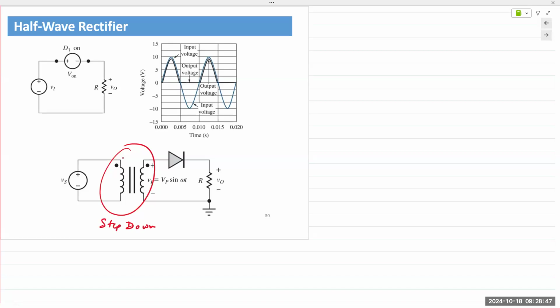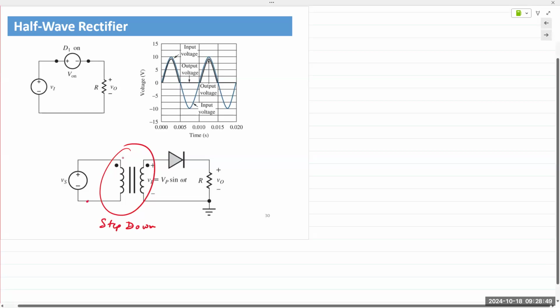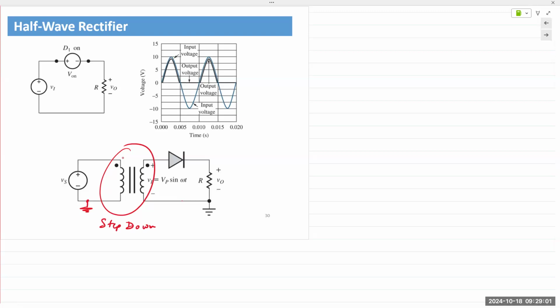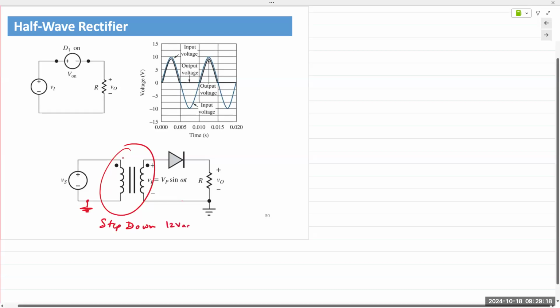They're all grounded. And so if they're grounded inside, if we connect an oscilloscope across the output, the bottom end would be grounded. So we can't actually see the actual waveform because it would short out one of the diodes. So we've gone back to how we used to do things back in my day. We are going to use actual transformers to step the voltage down from the power outlet to 12 volts AC. That's the transformer we're going to use in the lab.